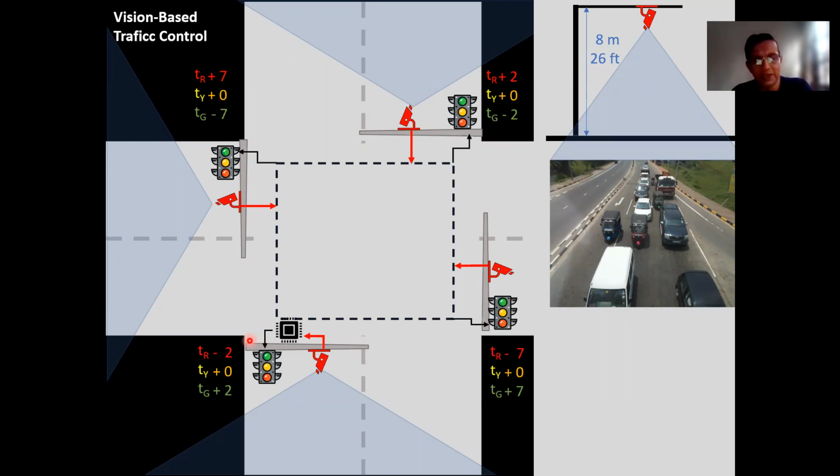because the vehicle dynamics change, new vehicles are coming in to the roads, every few months you need to collect data and look at the latest situation. Dynamics have already changed, and accordingly update the static timing. Even the static timing should be updated. And unfortunately, even that is not happening in Sri Lanka in an effective manner. So therefore, most of the intersections are running obsolete timing.